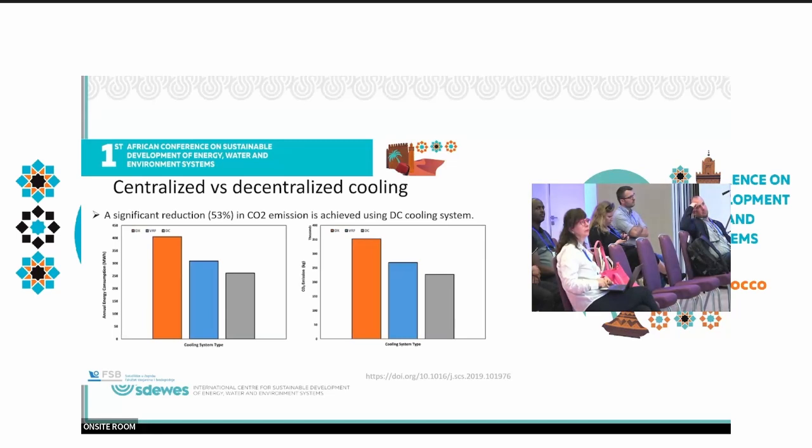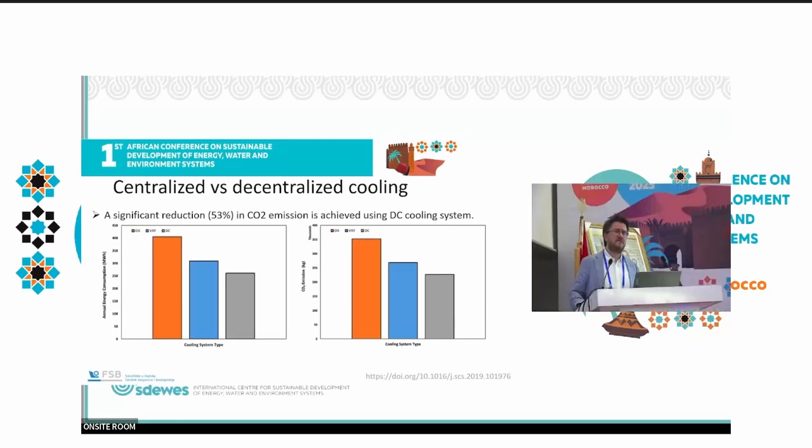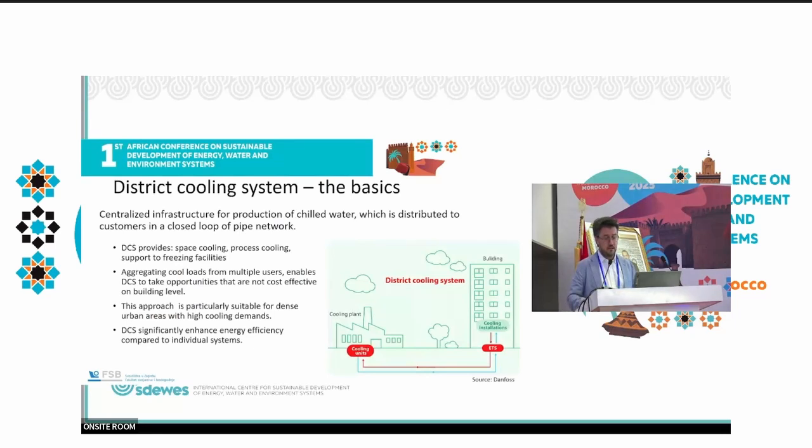Another thing worth mentioning is that within this research, a life cycle cost analysis was done for a period of 24 years, and it actually showed that district cooling systems are much more economically viable than individual units and systems. The difference was around, let's say, 22 billion for RTUs, 20 billion for VRFs, and 17 for the district cooling system, which is a significant decrease in economic parameters.